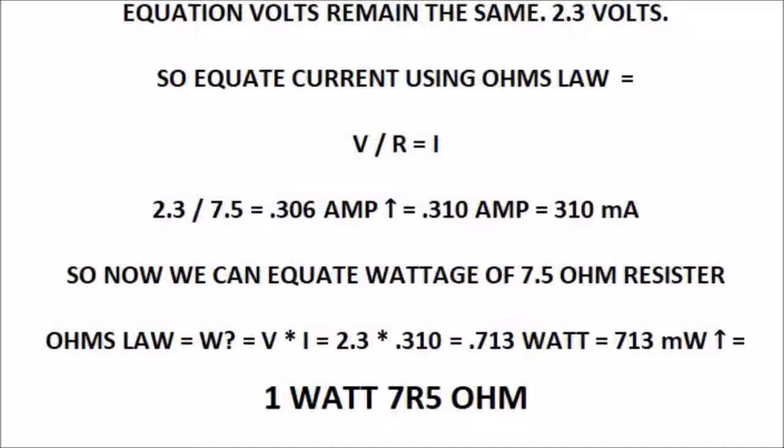But as you know, if you drive your car everywhere flat out, the engine doesn't last long. Well, it's the same for LEDs. If you drive them flat out, they don't last as long. This way, the resistor, being 7.5 ohms, is going to allow less current through the LED, so the LED will last a lot longer. Something that Big Clive always likes doing, making things last longer.